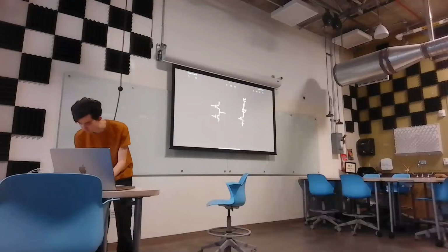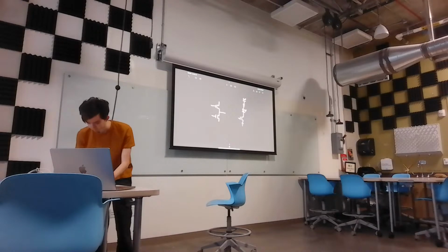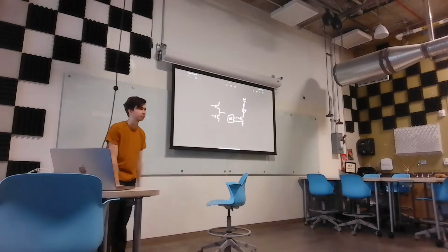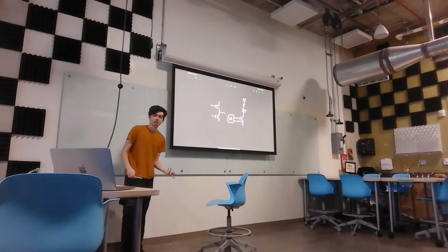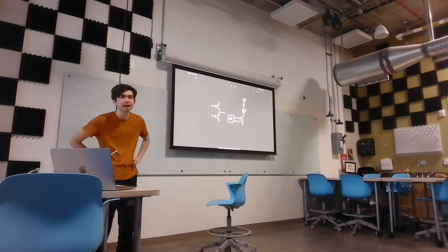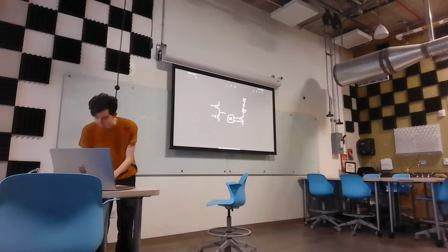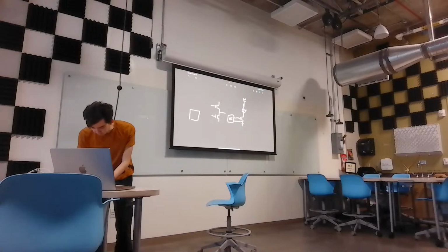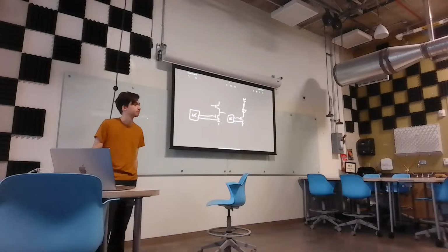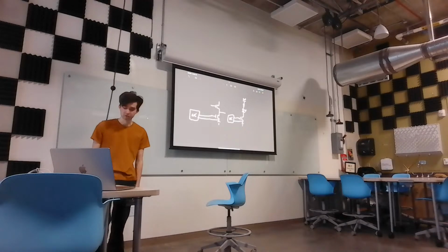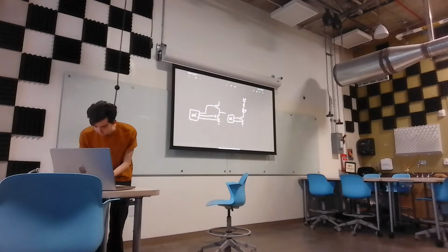And so in this case, it's super easy to achieve that voltage because you can just take a microcontroller and say, hey, output a signal, right? That's easy. Here's the thing, though. When we're doing this half bridge thing, we've got 2 FETs stacked on top of each other. If we have a microcontroller over here, and we try to send a signal here, all good, right? That's just like over here. Where it gets tricky is if we want to send a signal here.